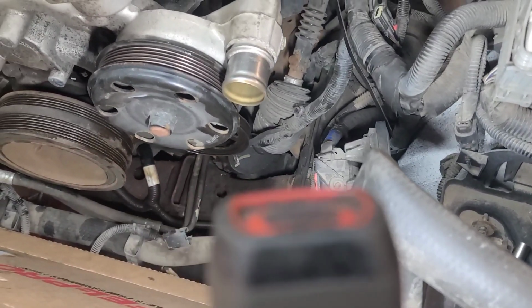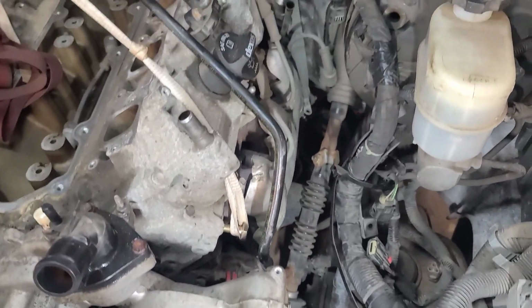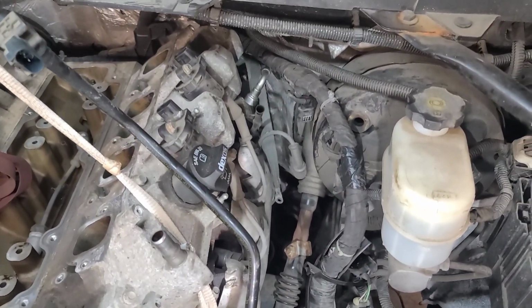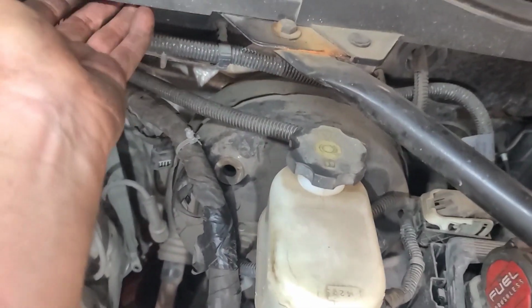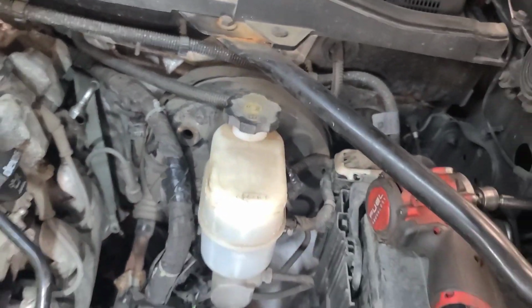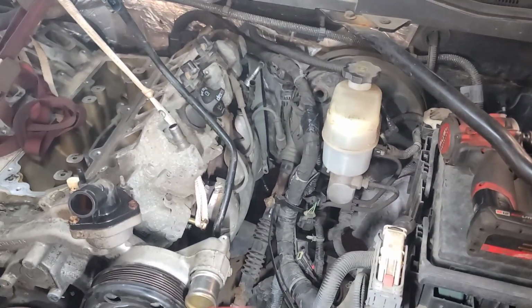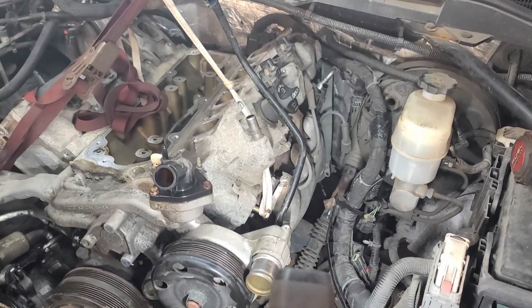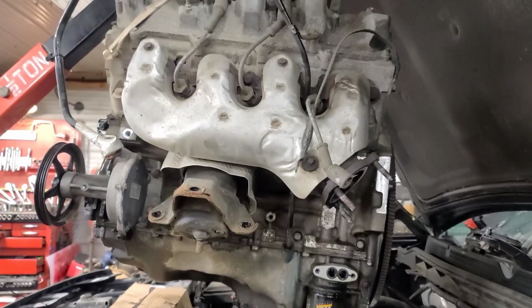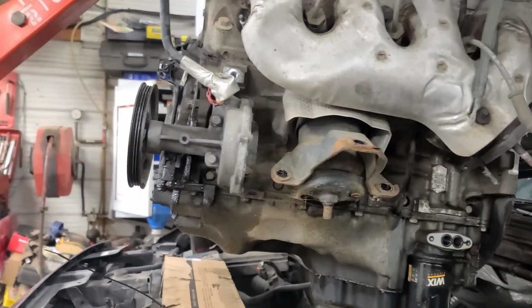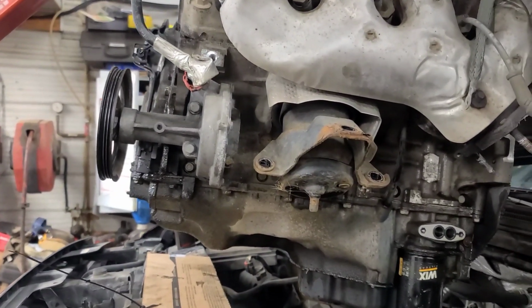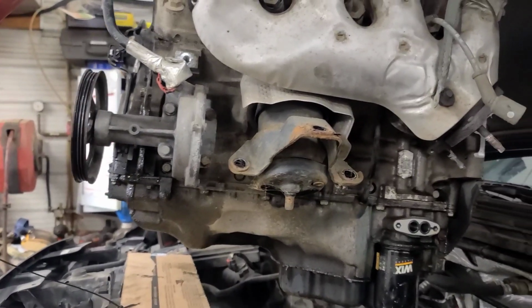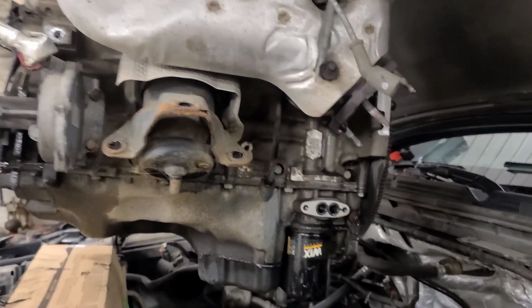Even if I try to turn it, I can't get it up. I took the back coil off at the back corner there to give me a little clearance on the firewall. This is steel here, so it doesn't come off. This is fighting me all the way. Well, it just barely comes out of there. Take the harmonic balancer off. I didn't want to take off that vacuum pump, because I need a new gasket for it, but if you took off that vacuum pump, it'd give you a little bit more clearance.